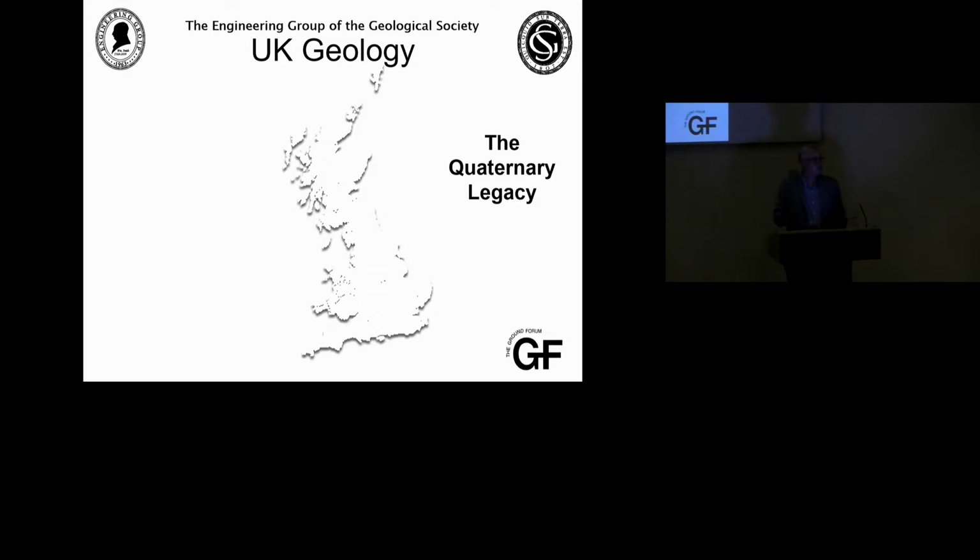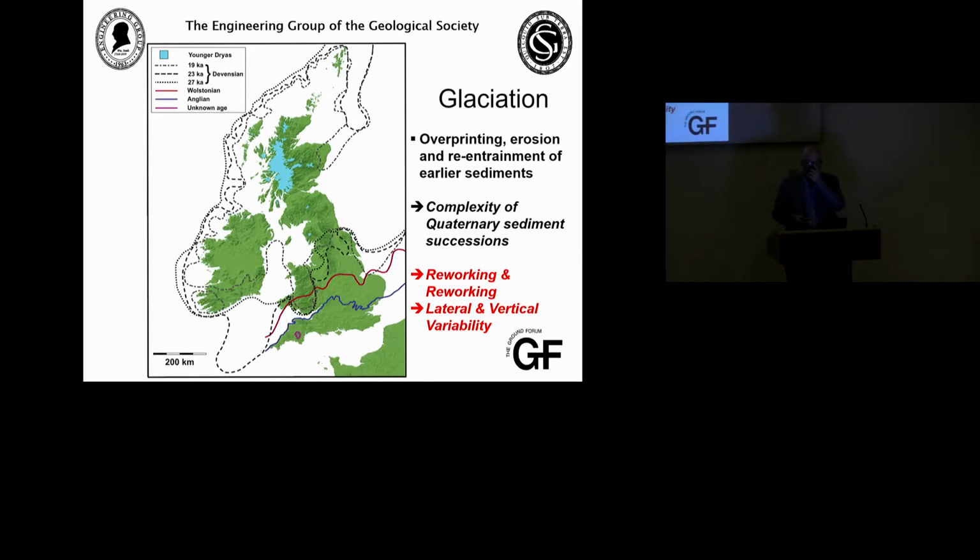Even in London today, we're starting to more fully appreciate the influence of Quaternary conditions on that subsurface development in terms of the periglaciation, in terms of isostatic recovery, groundwater change, all happening in this Quaternary environment. So it's an extremely important period for ground engineering to fully appreciate that variability that's actually present within those conditions.